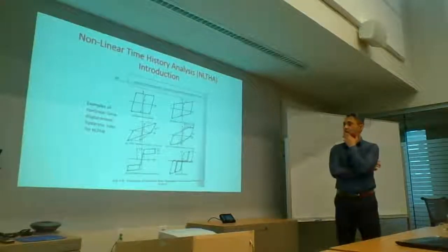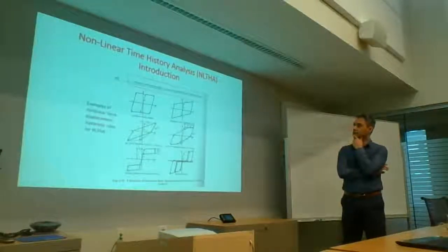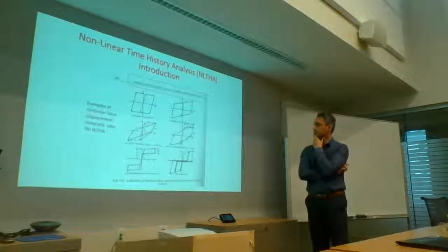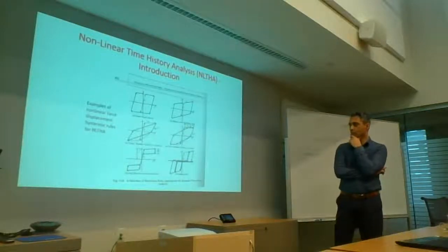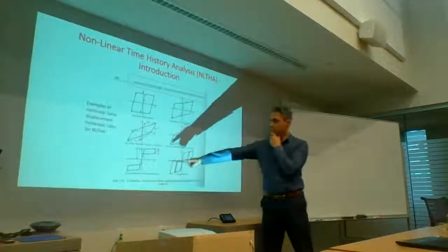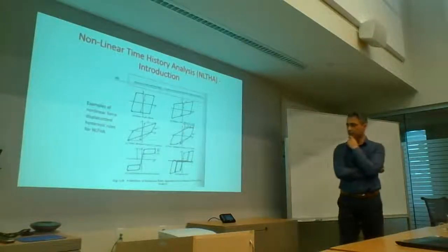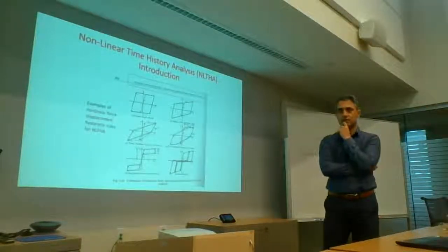There are lots of different hysteretic rules. The elastoplastic, this is coming out of Dr. Priestley and Calvi and Kowalski's book from 2007. You can look at a lot of these different models. This one is quite interesting. I think Chi has been doing some work on some models that incorporate the flag model with pre-stressing steel in there.